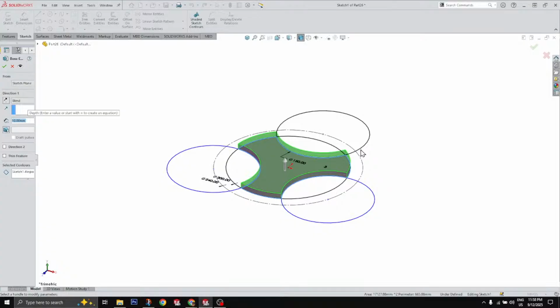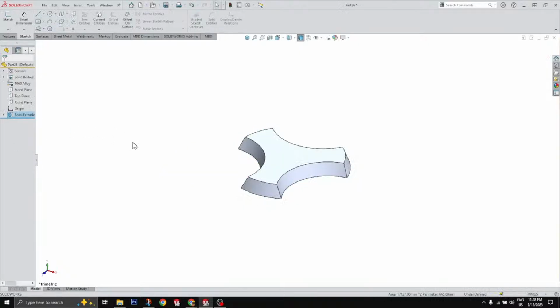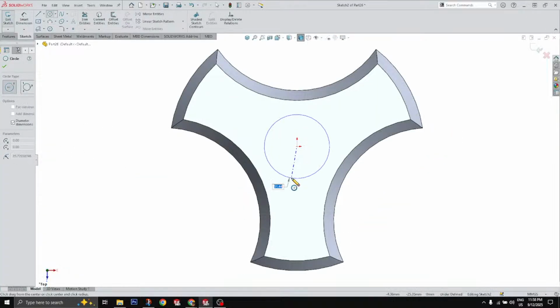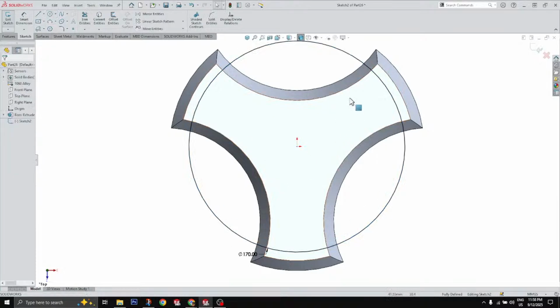And Ricardo Jean looks like he's going to start out by doing an extrusion, drawing first blood with that first extrusion. He's decided to create that tab shape first, and now it looks like he's jumping into a circular pattern of that tabbed shape. So he does a circular pattern, realizes he did 4 instead of 3, and then redoes it. He did it with a body. When you do a circular pattern of a body, it does not combine, so he had to do an extra combine afterwards, but he was ready for it. It didn't slow him down at all.